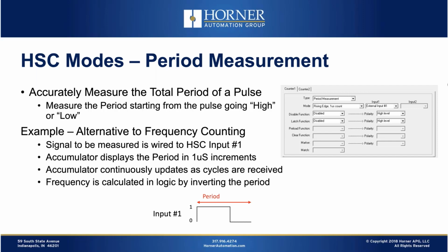And then again, as cycles come in, not just pulses, because it's an on and off part of the cycle, the accumulator is continuously updated. As those cycles come in, the period in microseconds is going to be reported by the accumulator. Again, a simple application there.